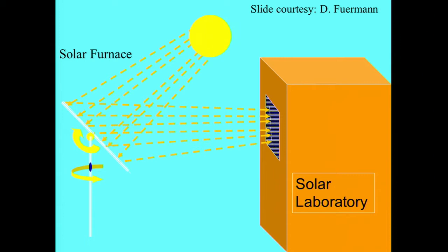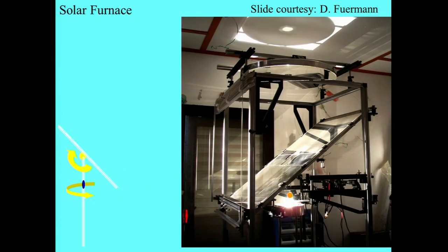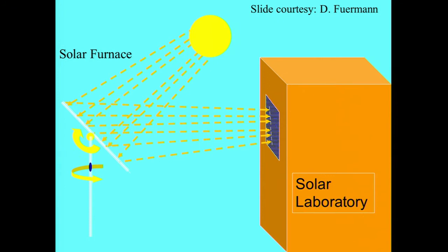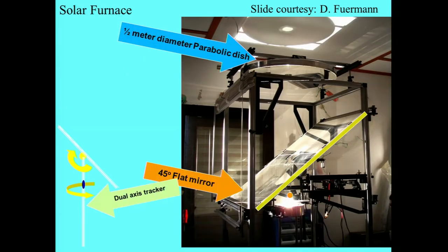For this, we use another completely different system without the fiber. The system is the following. Outside, there is a flat heliostat which tracks the sun and sends parallel lines of light to the laboratory, to the window. Here there is another flat mirror which redirects the light to a more or less big parabolic mirror. In the focus we have 15,000 suns.